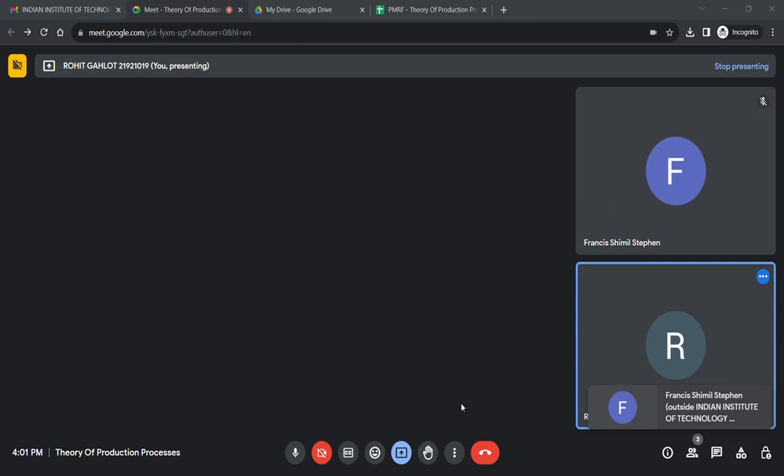If we calculate with that formula for a side riser, we will get V by A as D by 6. Now let's calculate V by A for our casting. Generally in every problem we need to calculate V by A for our casting and V by A for our riser. Then we always equate that the V by A of the riser should be greater than V by A of the casting.